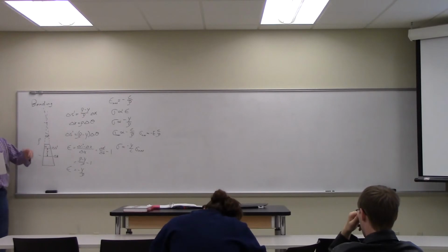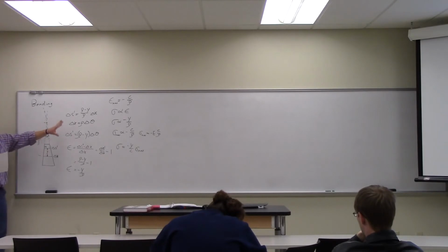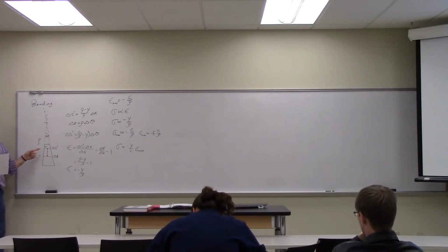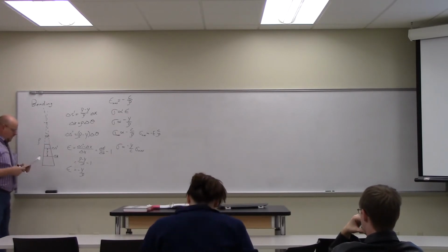At least to a first approximation, until we get to really severe bending, it'll be a little bit different. But as long as we're working in a linear elastic regime, there are no shear stresses. Everything is a normal stress. Okay, so this is all we need to worry about. We don't have to worry about tau. There's no taus generated in this configuration.